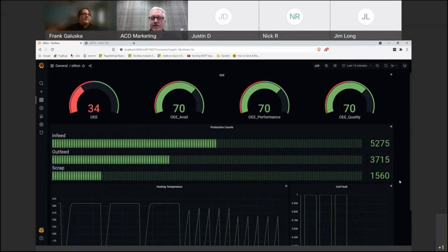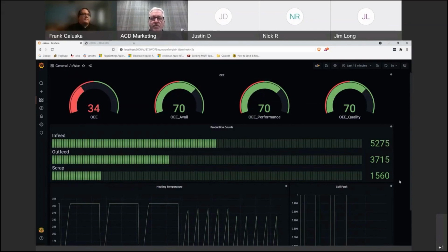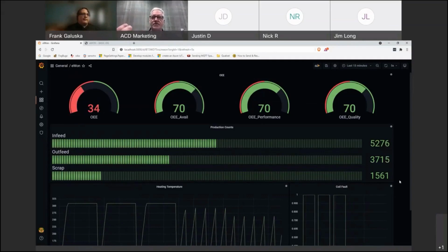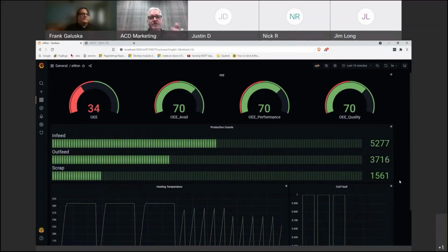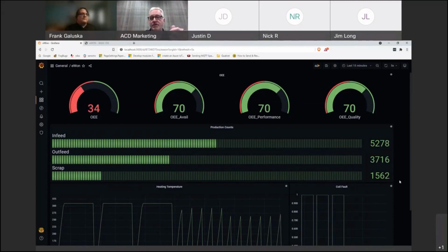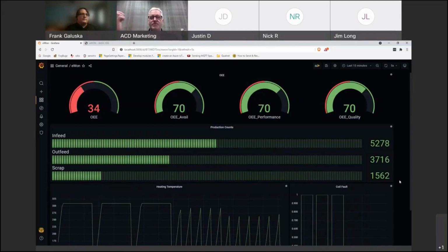Good. So one more thing, and then I think you have a couple more things to get into. Once that data is in the data broker, really it's no holds barred as far as how you want to use the data. Get it into a historian, get it into a product like Factory Studio or frameworks from TatSoft or Ignition, or get it into any other kinds of products. You could connect a lot of different products to that data broker to publish data, to get more data into that data broker, to add more context to the data, and to subscribe, to pull the data and analyze it and push it in again.